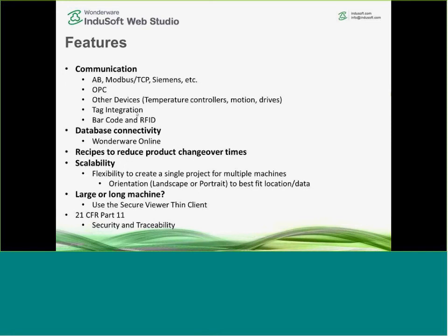Tag integration is a feature that we have for some of the drivers to allow you to pull in the tags directly from the PLC, pull in the I/O addresses so you don't have to configure that. We have connection to Wonderware Online, one of the things that's cloud-based, and this tool is really kind of nice. You don't have to really build anything. You just tell it what you want to go to, and then you can pick the type of charts you want to look at and dive in and analyze that data.